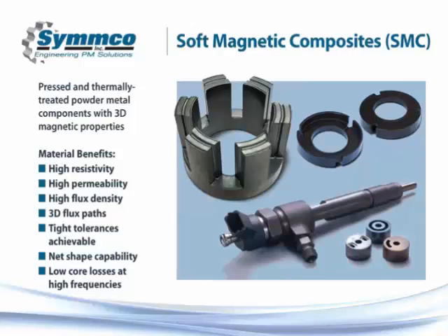There are some materials that are much more stable. So if we're talking a hole diameter going through a part that's, let's say, an inch in length, we're probably going to hold 0.002 to 0.0025 total tolerance, 2.5 thousandths. OD is very similar. The larger the diameter, the more tolerance we need, simply because of OD variation.